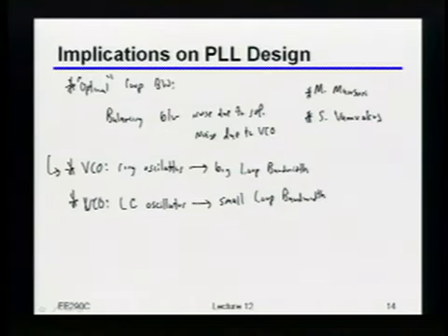Yeah. What's the limiting factor of the frequency of the reference? Right now it's very practical. If you want to buy a low-cost crystal, the best reference you can get is about 500 megahertz or so, if you're coming straight off the crystal. Now, you could buy a reference that gave you something higher than that, so maybe it internally had a PLL. But remember, the reference guys want to make money, so they want to build something very highly programmable that covers lots of different frequency ranges. So they usually have a ring oscillator inside there too. So if you bought a reference that was 10 gig or whatever, but it was a crappy ring oscillator reference, then you haven't really bought yourself all that much.